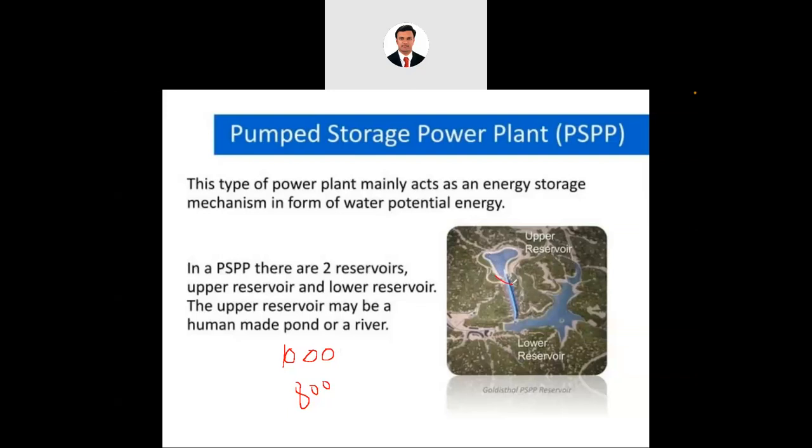So you can see here in this diagram also, there is an upper reservoir, okay, and there is a lower reservoir. So at the normal condition, this particular hydroelectric power plant will be producing some 1,000 megawatt. Now during the daytime, the demand is only 800 megawatt. So the excessive energy, that is the 200 megawatts, we have to store this excessive electricity, right? So for that, during the daytime, we pump back this particular water through these channels into the upper reservoir, which is at the higher level.